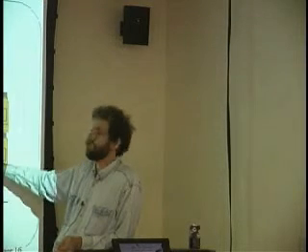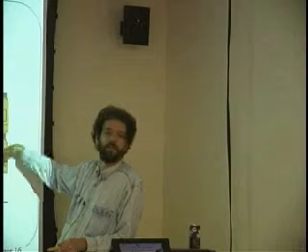So you can improve throughput not only by pipelining, but also by parallelism as well, which is the idea of having 2 sets of these, and furthermore having 4 of them in a row that you feed 4 into at the same time. So you see here 2 kinds of parallelism. One is 4 simultaneous being used at the same time, expanding the amount of hardware by a factor of 4 and clocking all those in at the same time. And the other is called round-robin parallelism, where we expand the amount of hardware by 2, and we alternate back and forth between these 2.